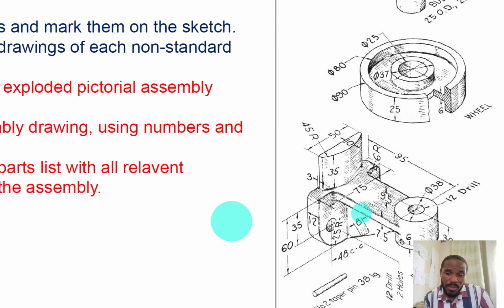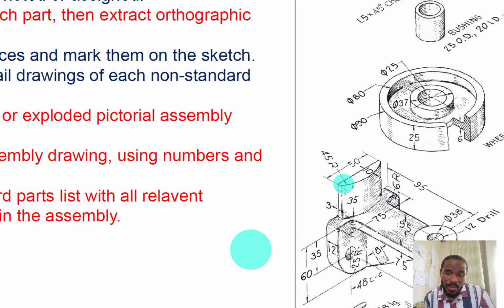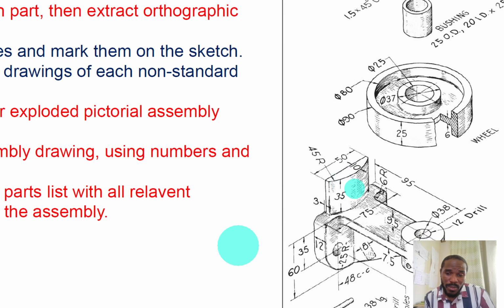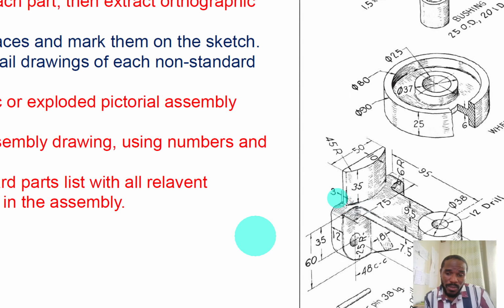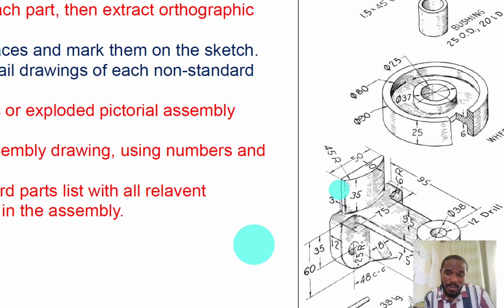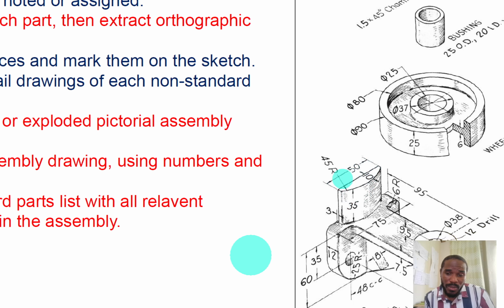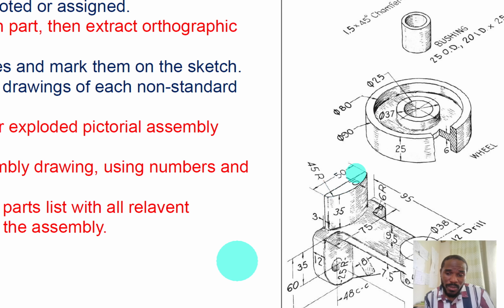Great. So having done that, I want us to now do this feature before we come to the cylinder. This feature here. Now, when you look at it, there is a distance of 3 millimeters from the end of that to where this feature starts, right? That's the first thing to note. And then the feature has a length of 50 millimeters, right?